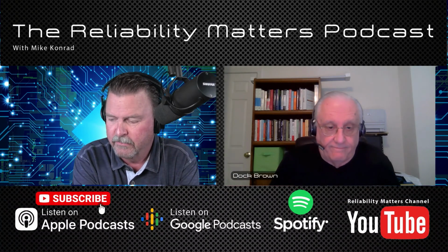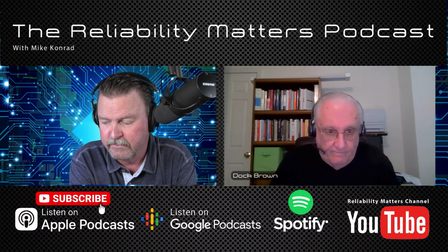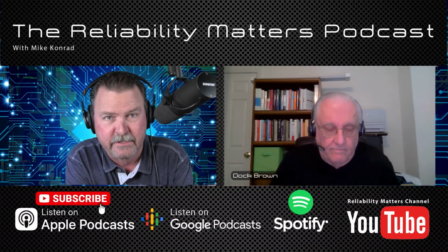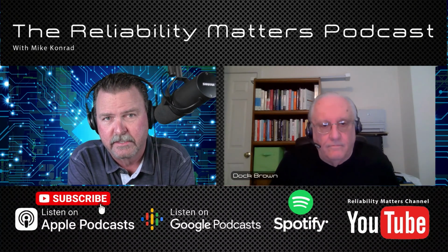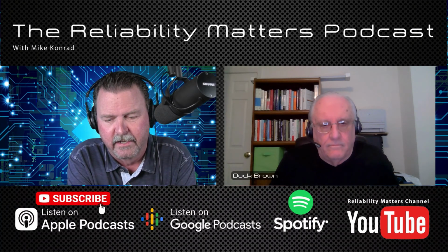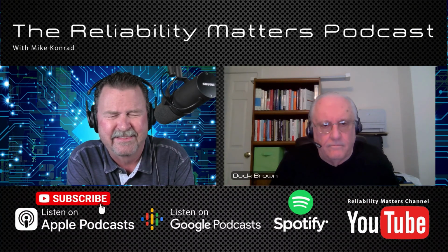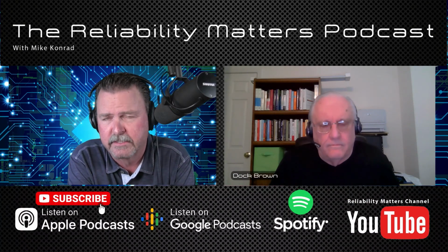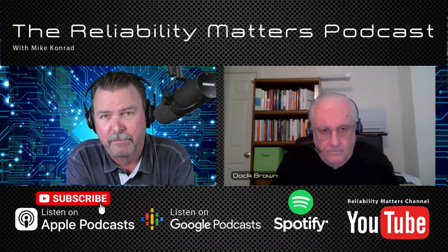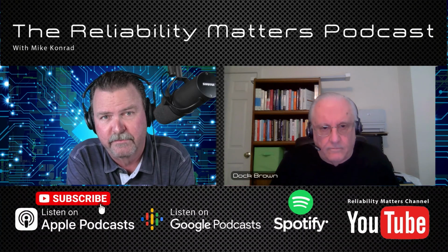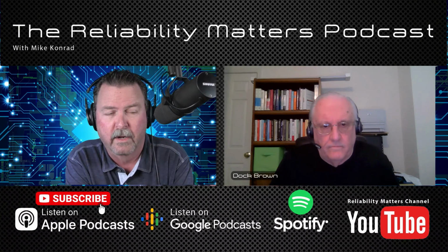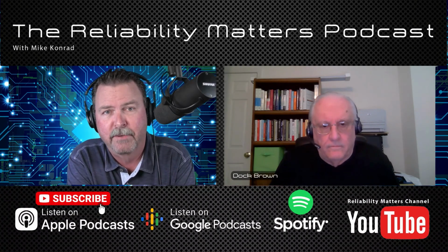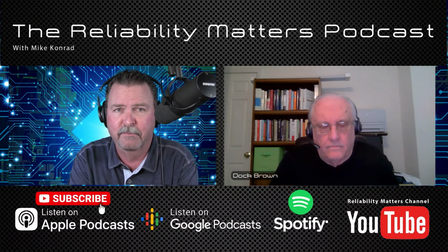Absolutely. And then the last kind of takeaway, I'll throw in a little anecdote. You were talking about flux activation, encapsulation, things like that. Our friends at Foresight Analytical Laboratories in Kokomo, Indiana, recently did some testing, and they ran boards. I think they were B-52 boards, test boards. They ran these test boards at the proper peak temperature for the materials they were using, which was 250 degrees C, and then extracted whatever residues there were from under various components, subjected them to ion chromatography, established the baseline,